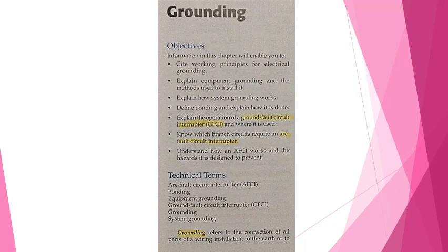Grounding basics. Grounding protects by limiting the possibility of damage to electrical equipment and conductors and by preventing shock to persons contacting electrical equipment. Electrical systems could receive extremely high voltage from several sources. One of them is lightning striking electrical wiring or service wiring, figure 9-1.